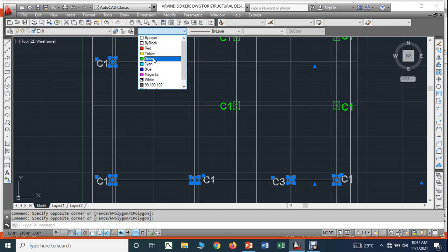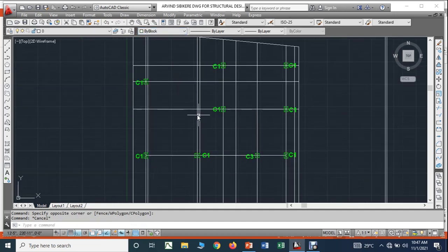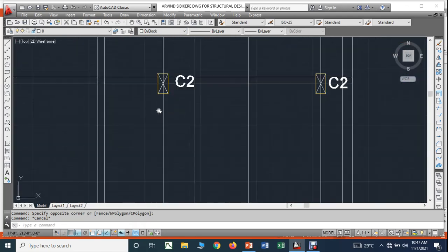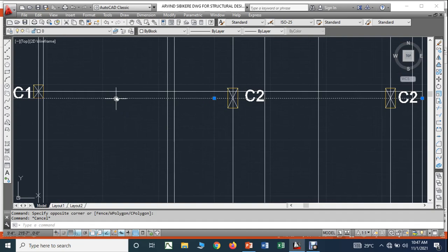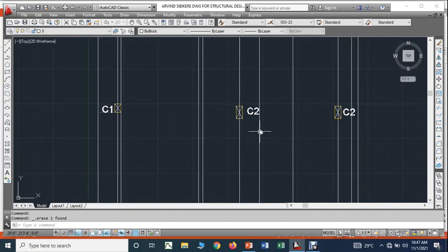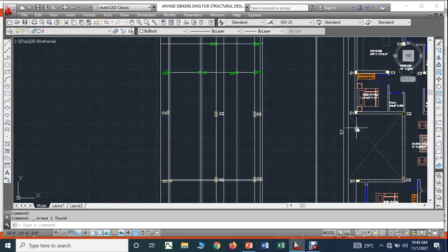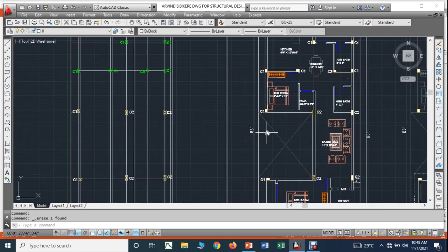Right. Yes, so indicating that all these columns are okay. Now let us see here also. Here also, if you see, students, only our two columns are in line, and the other two columns are not in line. Here also I will check whether any issue will come. Yes or no. Now you can see they have clearly told nothing should come in this boundary, therefore I cannot shift this column, but I have an option to shift these two columns, no issues.